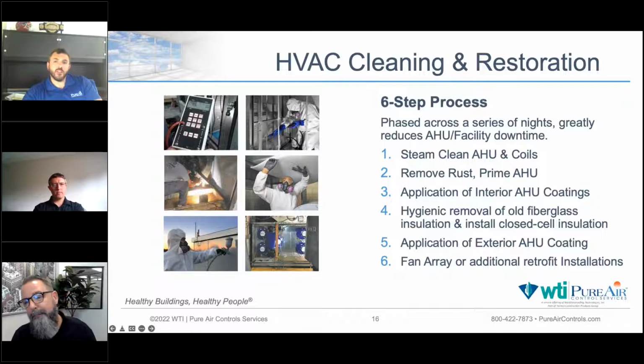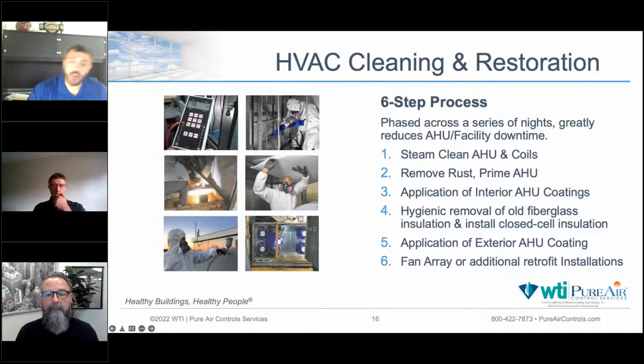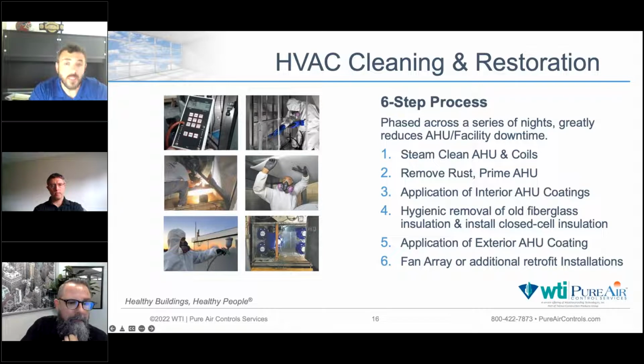Yeah, you see here six steps in what may be a typical air handler restoration. I don't like to use the word typical really, because every air handler tells its own story. It's based on the air handler condition assessment and the factors I talked about earlier. What does it serve? What's appropriate in terms of investment back into that air handler because of the criticality of the area it serves, or because of its location, because it can't perhaps be replaced since it's in such a poor location that the logistics to replace it would be extremely expensive? Maybe a tight mechanical room, maybe a difficult to access roof area. So every air handler restoration is different, but this is one that's fairly common.